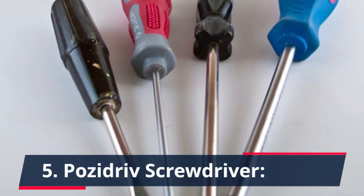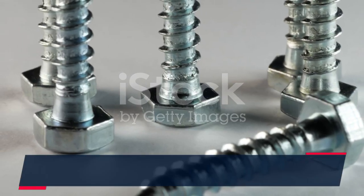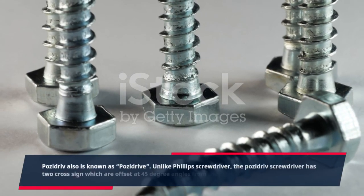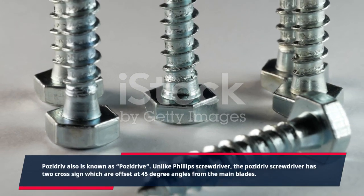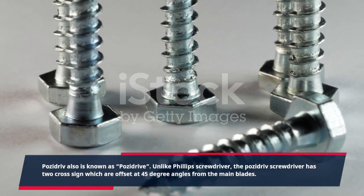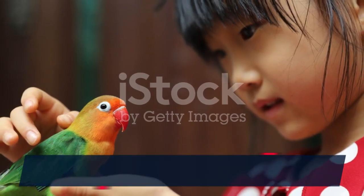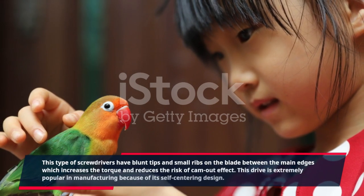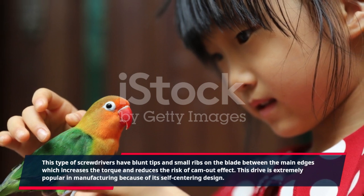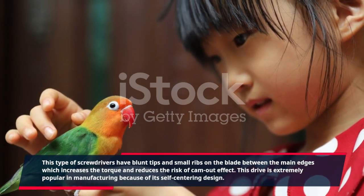5. Pozidriv screwdriver. Unlike a Phillips screwdriver, the Pozidriv screwdriver has 2 cross signs which are offset at 45-degree angles from the main blades. This type of screwdriver has blunt tips and small ribs on the blade between the main edges, which increases the torque and reduces the risk of cam-out effect. This drive is extremely popular in manufacturing because of its self-centering design.